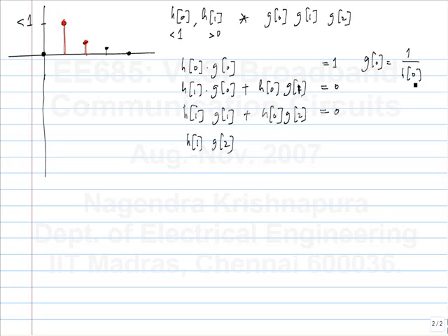Okay. In order not to reduce the BER, it's not enough to have a single cursor and all the others 0. The amplitude of that should be sufficiently high. That's what we are trying to do here. We will assume that there should be 1 and these two should be 0. And what is G of 1? Minus H1. And what is G2?